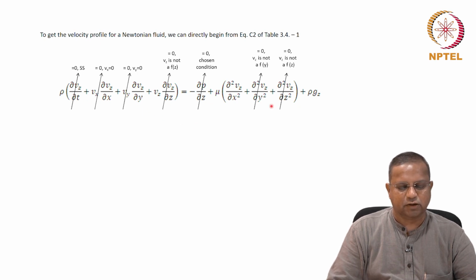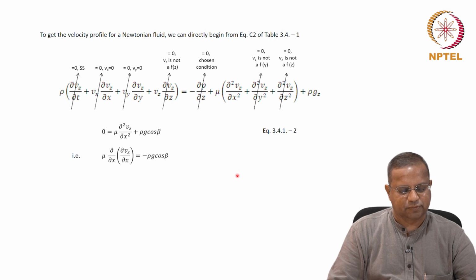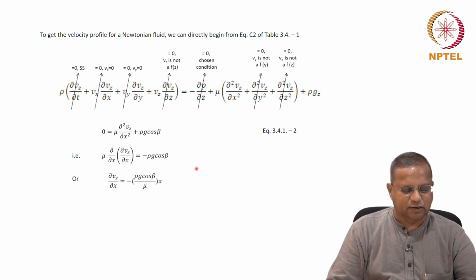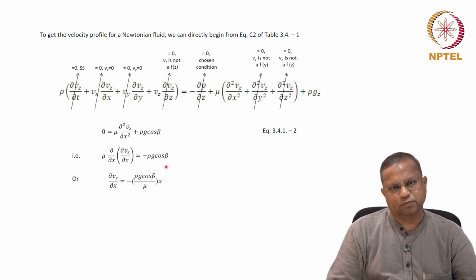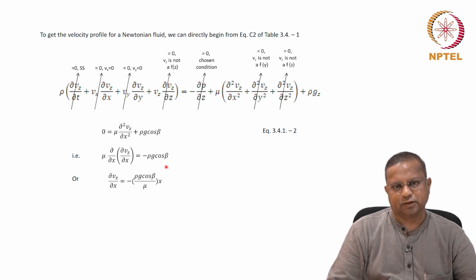Again, one step, you take the velocity equation, cancel out the terms, and then we got the same equation as the earlier case for getting the velocity as a function of x. Or this one was the expression, the same expression that we got earlier. Okay. So it's much easier to use the conservation equation approach is what we said.